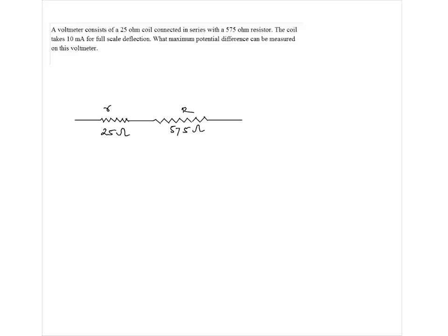That capital R is part of the voltmeter. So we say the voltmeter is connected across 2 points. Capital R is part of the voltmeter, so the voltmeter will measure the potential difference across these 2 points. The maximum permissible current is 10 milliamperes through that coil. Because capital R is in series with the coil, 10 milliampere will flow through that also. 10 milliamperes, 600 ohms. It should be a very simple question to answer.